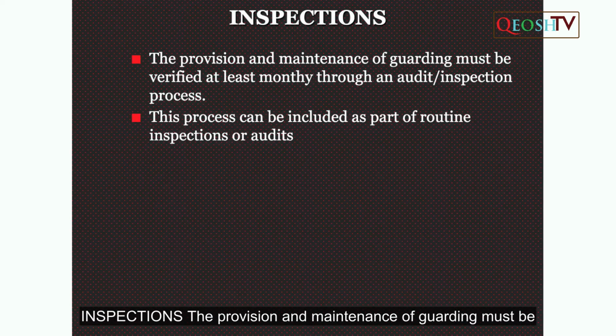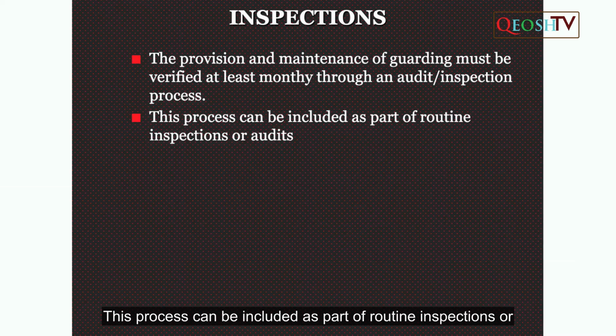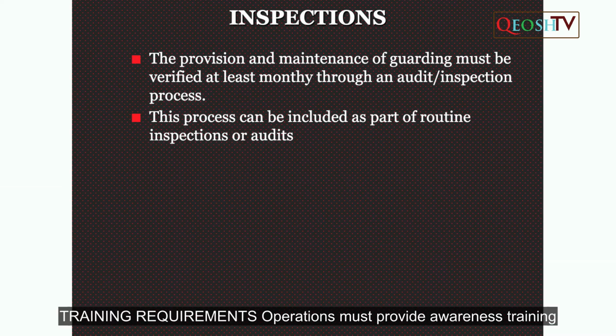Inspections. The provision and maintenance of guarding must be verified at least monthly through an audit inspection process. This process can be included as part of routine inspections or audits.